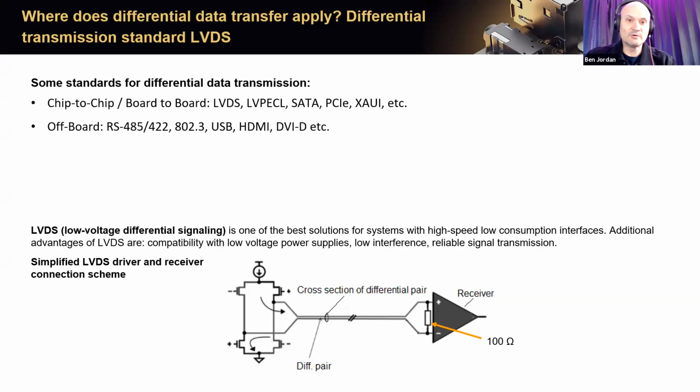As of DDR2 and later, there's a feature called on-device or on-die termination, or ODT, and this provides the termination of some of the high-speed lines actually in the die of the chip, and you can enable or disable that when you configure the device on power up.